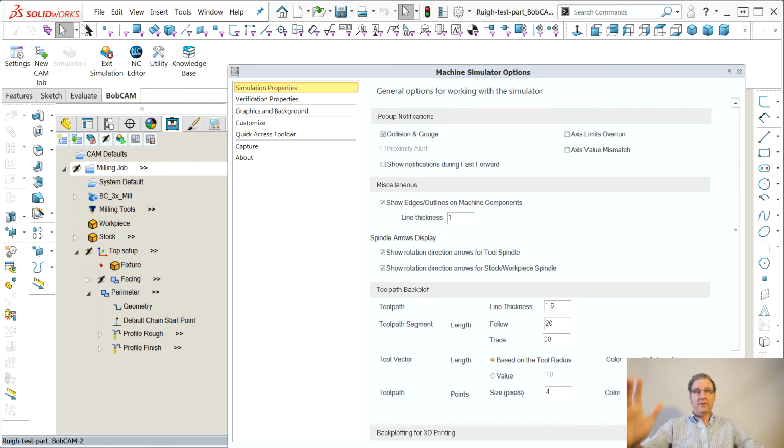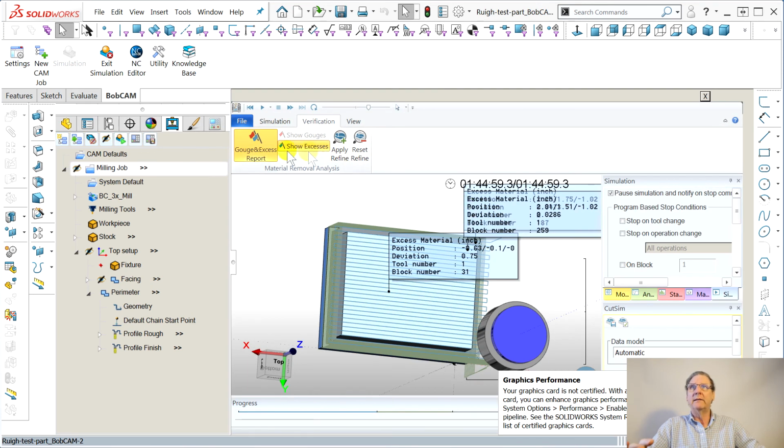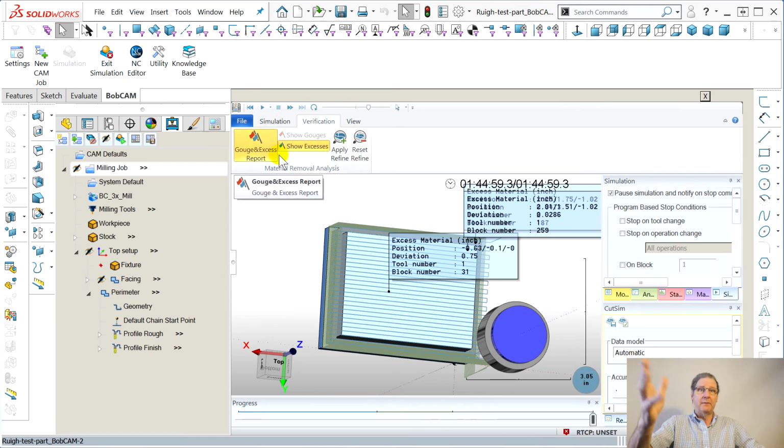So yeah, everything will be green, but you'll see, it'll be a few shows before we get to doing some of the 3D-ish stuff. But it did a little gouge and it just passed because it wasn't an 8,000ths deep gouge. So I wish I could find that for you real quick, but we'll play around. It'll be in here somewhere where it shows. And I tried, I went in options. It's like, tighten it up. Give me an accurate simulation. I couldn't find a way to get it tighter than 0.008.